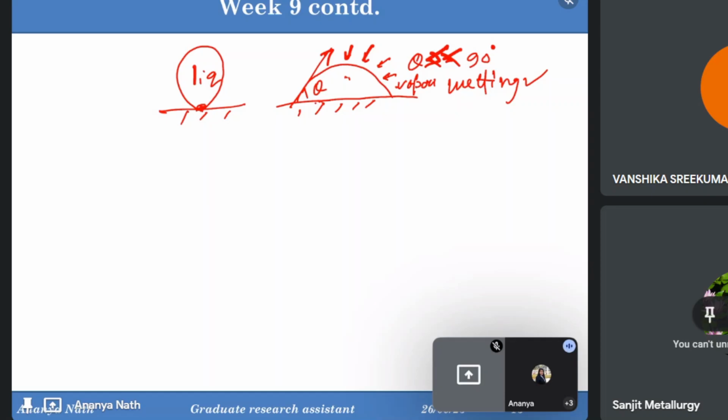So the next is magnesium. Magnesium reduces the aluminum surface tension and alters the solid liquid interfacial energy, because if the surface tension is very high, then it can hamper the wettability. So magnesium helps in that regard.